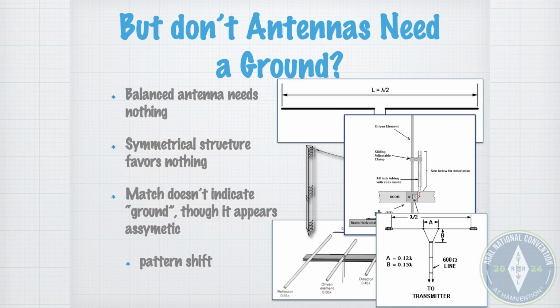It happens to be on one side of the antenna, but it could easily be on the other side, and it will affect the pattern just a little bit, depending upon its size relative to the driven element. So that hasn't found anything super interesting. In fact, there's this thing called the delta match, which is perfectly symmetric and does a similar job. So you can achieve symmetry if you really want it.